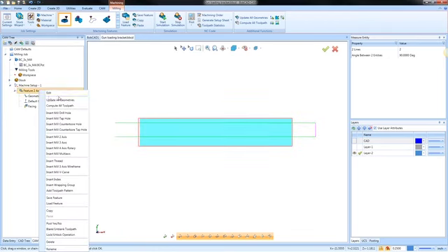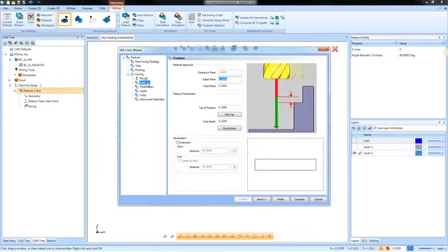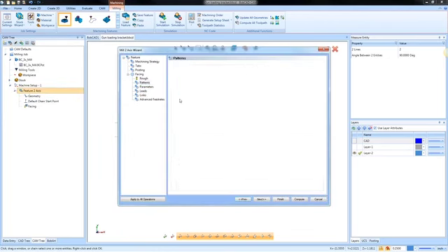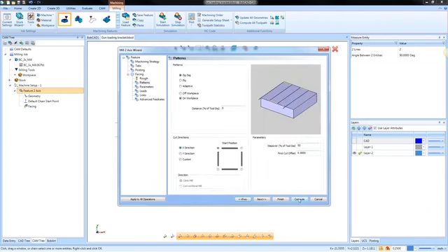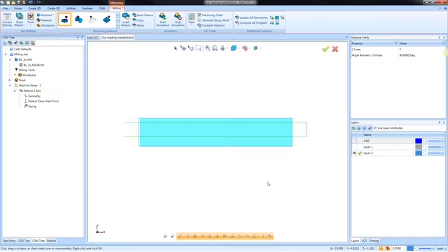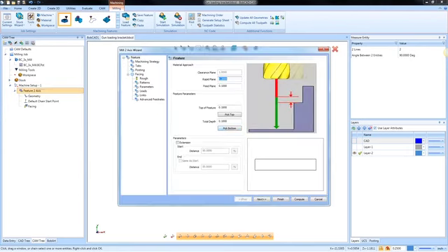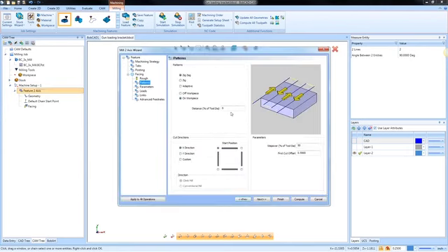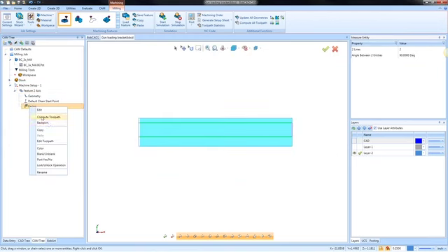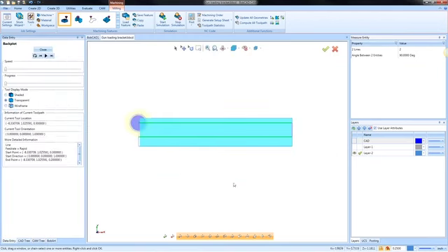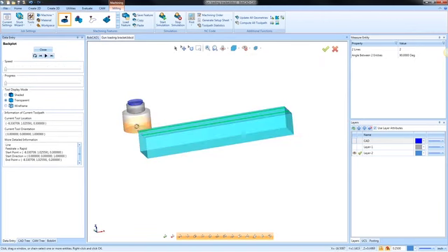So there are a couple of other settings here under facing. You have on the workpiece and off the workpiece. Okay, if you have on the workpiece, then the tool will stay on the workpiece. If you have off the workpiece, it goes off the workpiece. There's this distance percentage of tool. Right now I have it 0, so I could say 50% and recompute, and that will show the tool probably how you might have expected it, where center of the tool. This is for on the workpiece.